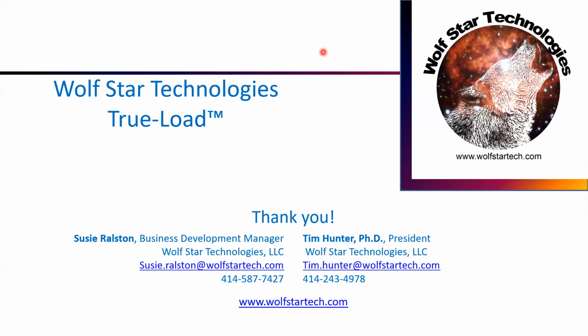So another person's talking about they've got structures and they like to put gauges on hot spots and do strain measurements in hot spots. TrueLoad by default does not work with hot spots. The problem with a hot spot is a hot spot's always hot. So if you're laying gauges in hot spots, we've got no capability to separate out the individual unit load cases.